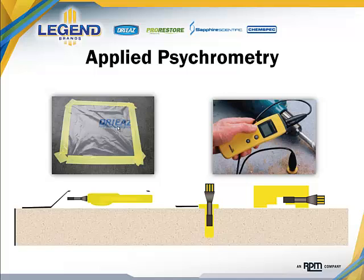This method of measurement traps the moisture to the surface so that we can get a measurement of how wet the building material is. And this is a pretty common measurement. It's something that we discussed again earlier as we discussed vapor pressure of building materials. This is another measurement where we're actually putting the probe inside of a dense material. Here we're evaluating again how much moisture is in the material based on the humidity that's being created. Again, down below, several alternate methods for doing much the same thing. These are all very precise measurements of humidity that are used to understand how wet a building material is.